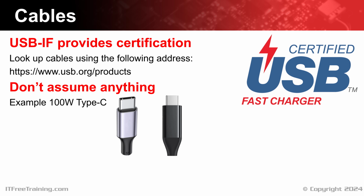Let's consider an example of two cables advertised as 100-watt Type-C cables. One assumption you could make is that it uses the Type-C connector, thus supports USB 3. This is not correct. One is USB 2 and the other is USB 3. The manufacturer probably won't advertise the cables as USB 2 because they want you to buy the cable. It may be in the specification or fine print or may be listed with a transfer rate of 480 megabits per second, hoping you don't read it or that you don't work out that it's USB 2.